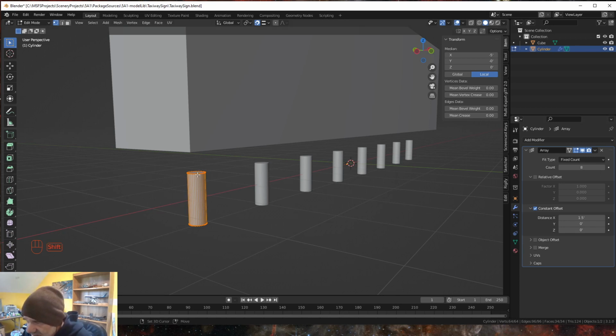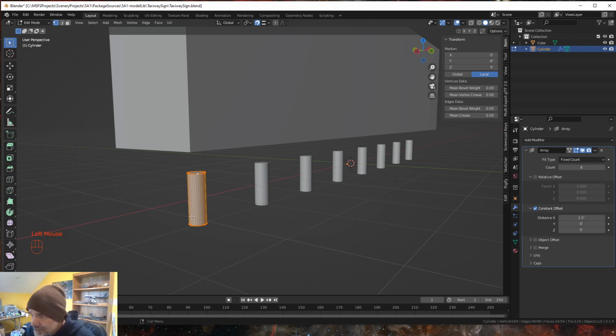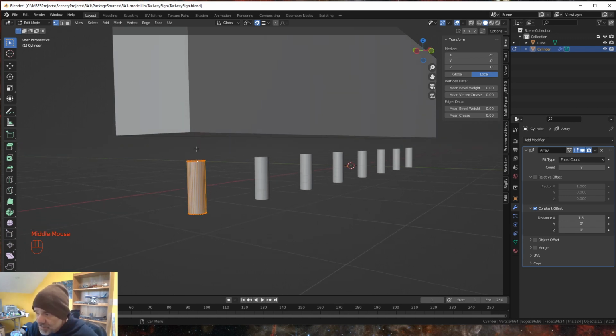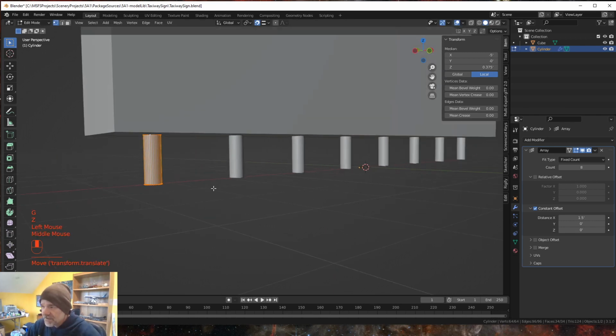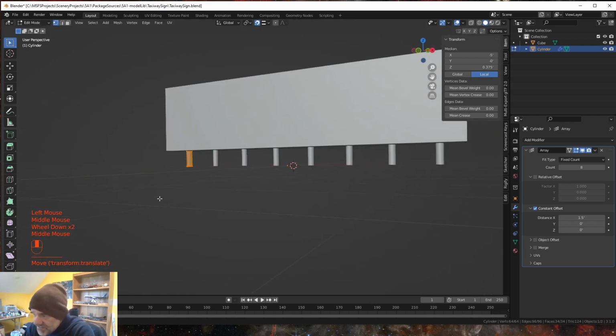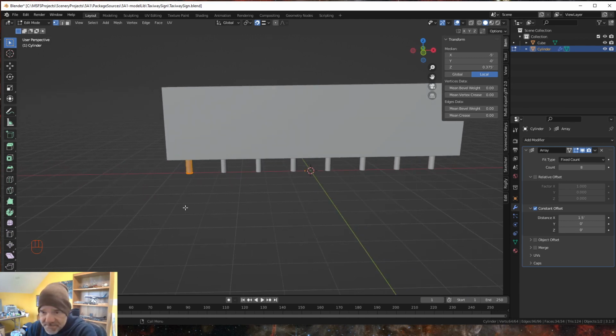I'm going to shift click this vertex here and select it again to make it active. Make sure I have active selected in my snap, and I am going to move that up until this vertex is on the same plane as this edge right here. So I'm going to GZ and then just snap to that line. Okay, so now our legs are in the right position.